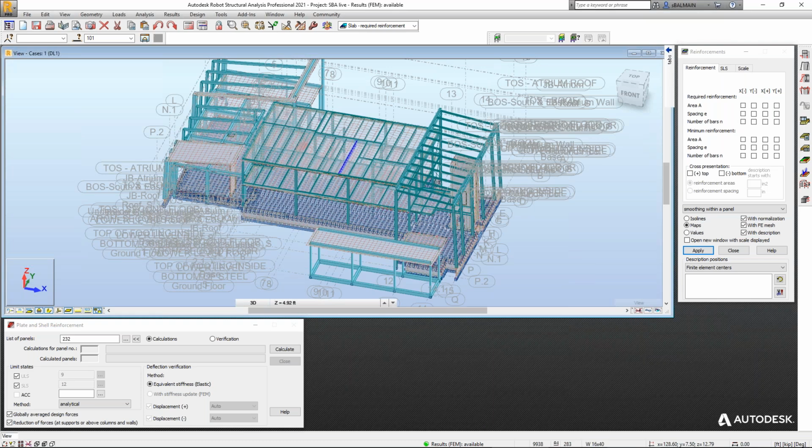But if it's a classic building with a lot of small elements, an alignment, etc., I prefer to start in Revit, because if I start in Robot, after I will need to realign or recreate all these small elements, and I'm sure I will miss some unalignment, you know.